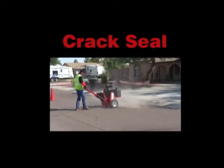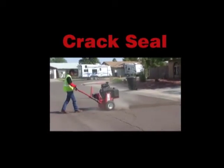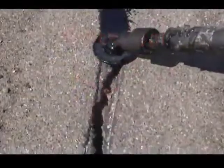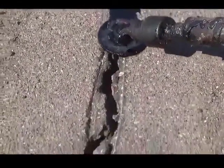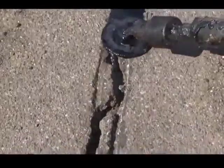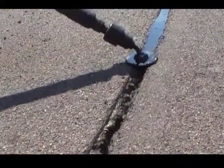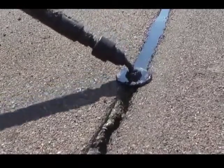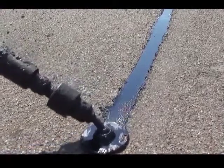The proper way to treat a moving crack is to crack seal, which is accomplished by routing the crack first, creating a reservoir to accommodate the sealant. After the crack has been routed, the sealant is applied using a sealing shoe or squeegee. There are various techniques which can be used to accomplish the seal. You can consult your Craftco representative for available methods.